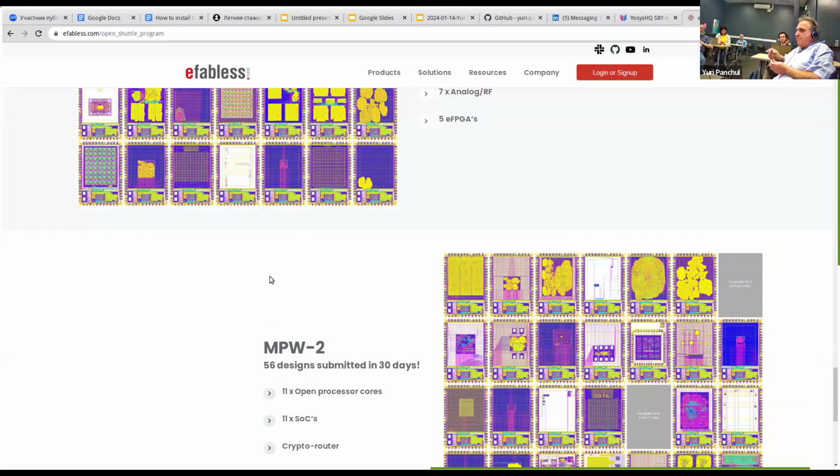To manufacture even in a commercial setting a 130 nanometer chip, you need hundreds of thousands of dollars. A 28 nanometer chip, which is good enough for even inexpensive old phones, was a standard in phones a decade ago. It's just a $1 million upfront expense in commercial, and just about $40,000 if you use the shuttle service.